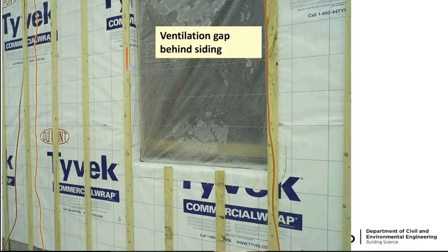We naturally create a gap. Now, the benefit of these furring strips, I think I mentioned, is that they mechanically attach this Tyvek commercial wrap to the wall. So it's not just held on with a small washer. No, it's held on with a 65 millimeter wide by continuous length piece of wood, which really anchors that membrane, even if we get 25 pound a square foot wind gusts or something like 1.2 kPa wind gusts. No problem. That furring strip will hold it.